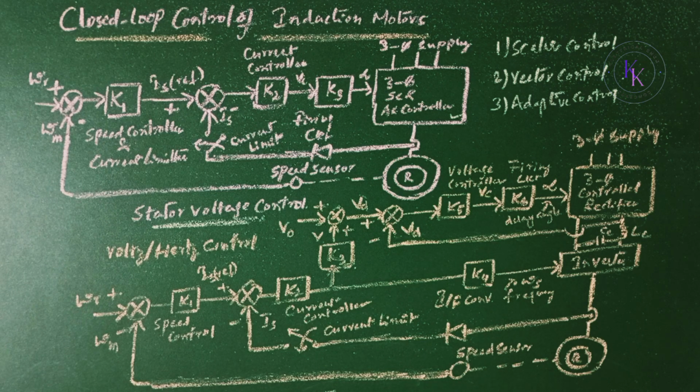In case of a PWM inverter, there is no need for the controlled rectifier, and the signal VD controls the inverter voltage directly by varying the modulation index. For the current monitoring, it requires a sensor, which introduces a delay in the system response.